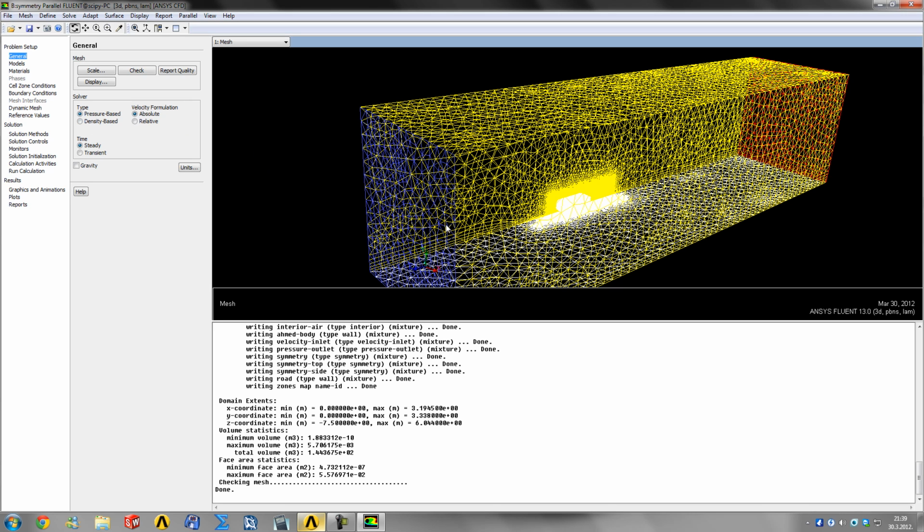If the vehicle was traveling at high velocities, such as approaching the Mach number of 1 or even above, then there would be effects like cavitation and density changes locally around the vehicle, and then you would use a density-based solver. Even though the pressure-based solver can solve for compressible flows, I think density-based is more accurate for that purpose.